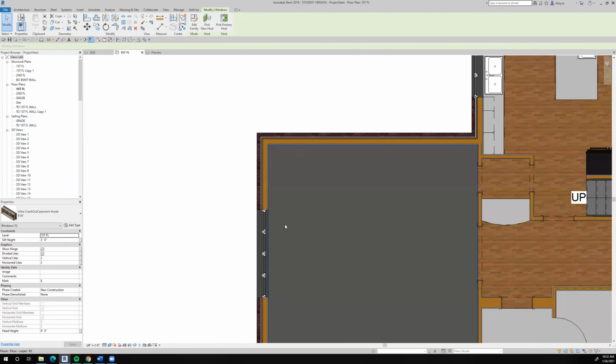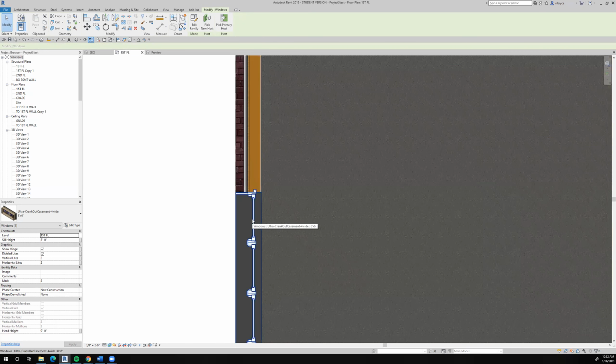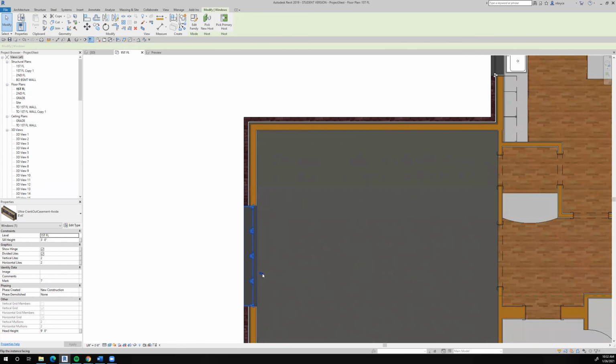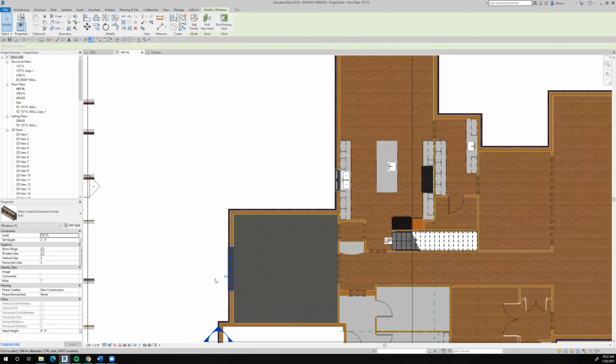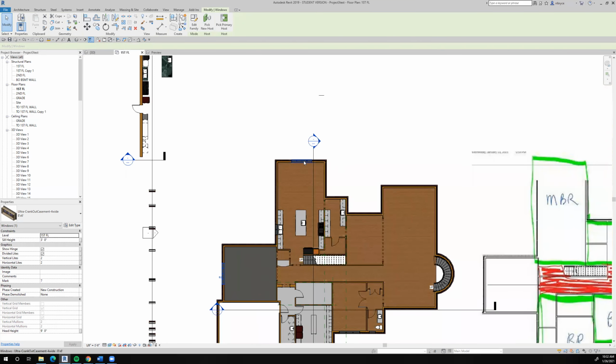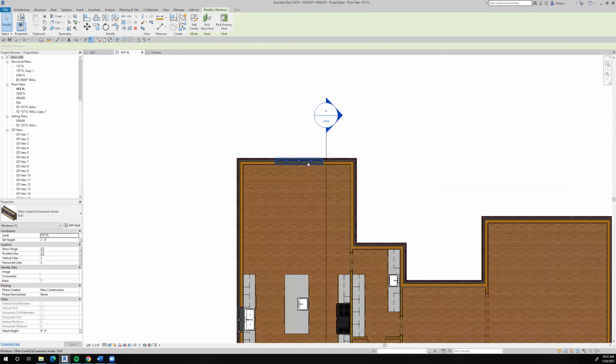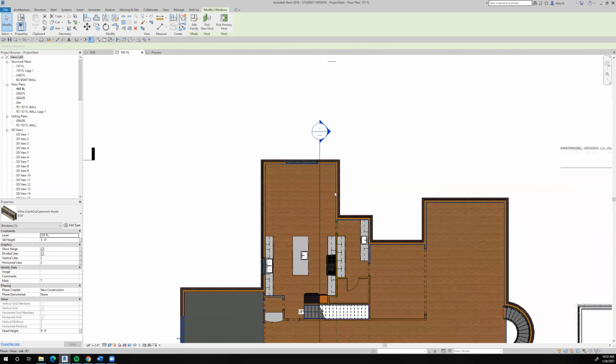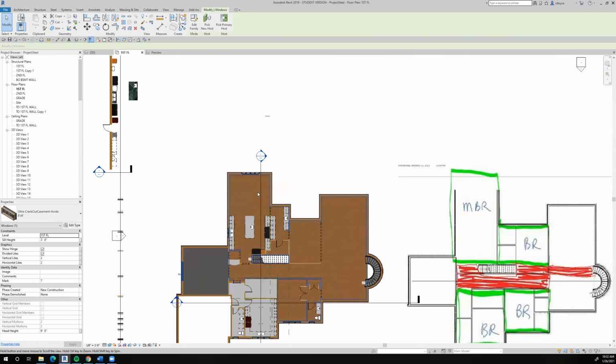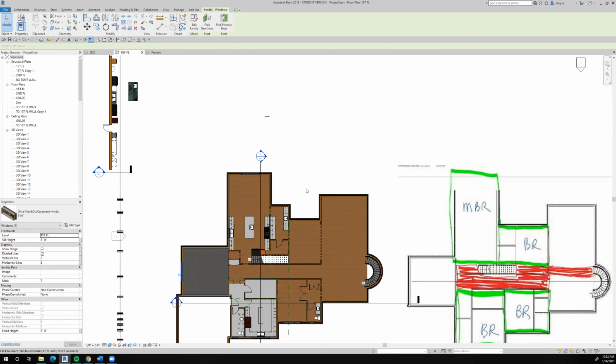And let's take a look at this guy now. The inset is correct, but he's backwards. So I'll click on this little arrow here. All right, so now I've got my 8 foot wide, 4 unit windows here. And now the question is, would I like another deck coming off of here? And I'm going to say no, I don't need a deck coming off of there.